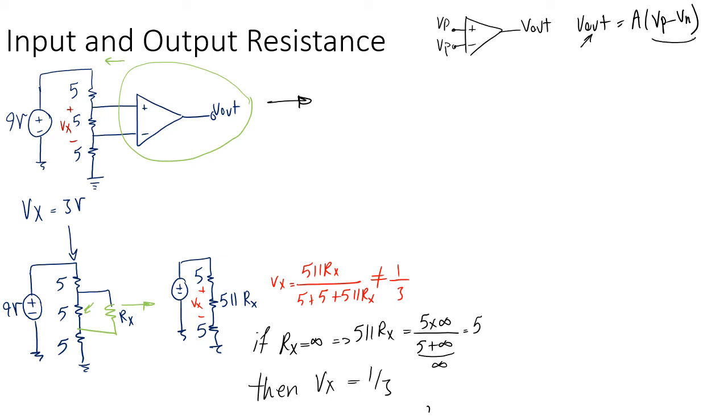And I know that if I want to do a proper measurement, the internal resistance of my voltmeter has to be infinity. In this case, the internal resistance of my voltmeter is the resistance that I see at the input of my amplifier. So this Rn has to be infinity if I want to do a proper job of amplification.